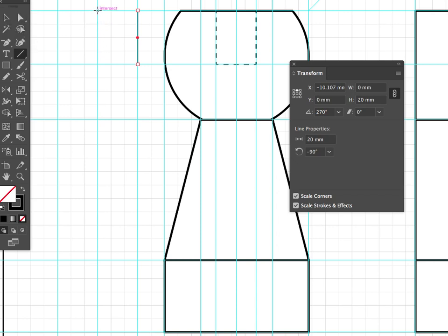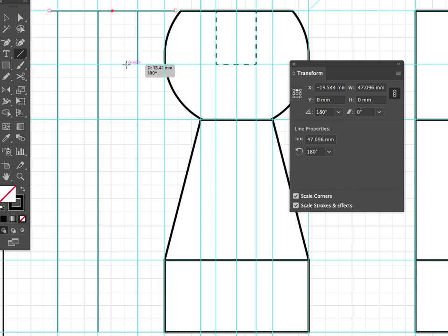You can either draw individual lines corresponding to individual parts, or if dimensions are just lining up, you can just draw one continuous line, then use the scissors tool to snip at the right lengths. Once we've done our vertical lines, it's now time to do the projection lines, which run horizontally, using the same method of intersecting with our guides.